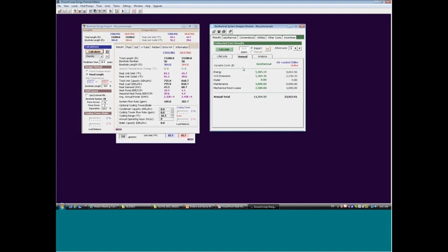We see, over a single year, what the variable costs are. The energy for the geothermal system is about $6,000 per year, and the conventional is closer to $10,000. Then the CO2 emissions in terms of dollars for geo and conventional, maintenance, and mechanical room lease. You can just see what a 1-year result is going to be. Then we can look at the different variables. We have our annual savings, our net present value savings, our annual CO2 reduction, which is about 20 tons of CO2, and then over 20 years, about 400 tons.